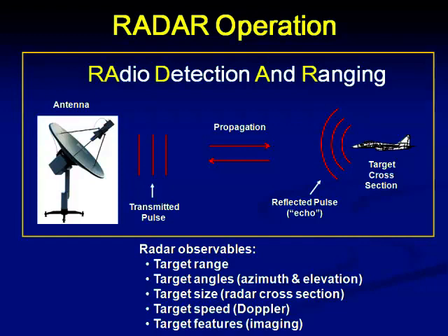The reverse of this takes place from then on, and you will receive the echo at the receiver point. The time taken is counted, and if you take the product with the velocity of the wave in free space, you will get twice the distance, as the signal has traveled twice the distance. So the time taken times the velocity divided by 2 gives you the range.